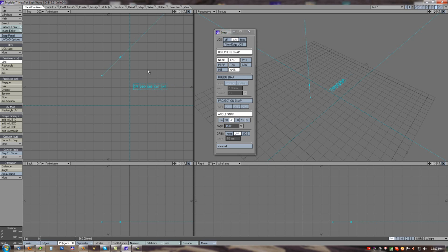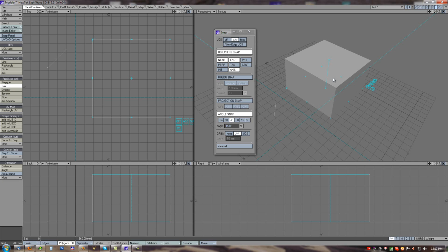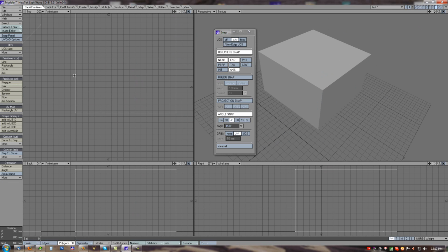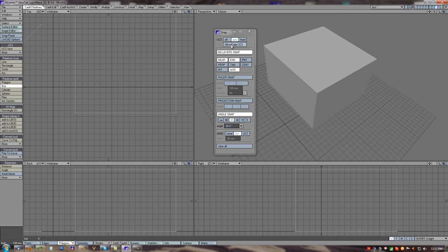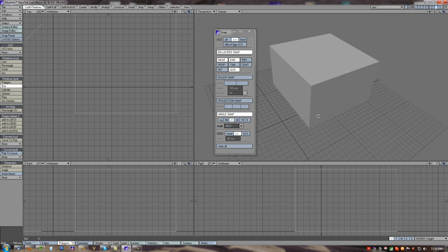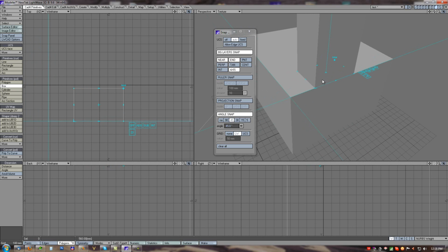So this is updated with axis snap, and another update is with the UCS system. When we have, let's say, this simple box, and use another tool or the UCS face tool, we can enable edge UCS, creating a UCS plane also from object edges. If it is disabled, then if we click onto an edge of the object, the UCS is always created from the nearest polygon.